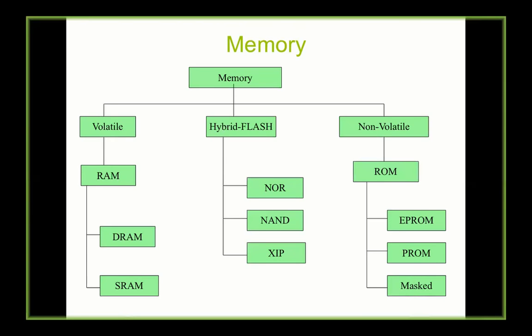So what I'm trying to say is, as a developer, when you look at a target hardware, and you see, hey, in this evaluation board there are 10 timers, but there are 2 DRAMs. So the first thing you should understand is, hey, I have only 8 timers which I can make use of. 2 of them are already going to be hogged by the DRAM slots. You getting me? Yeah, that's the perception.